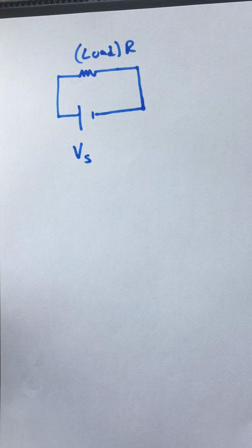Right? This is pretty standard at this point. I'm hoping we're seeing our way through it. Nature hates change, right? So any EMF induced in the coil is going to be such that it tries to counteract the change in flux. The upshot of that, mechanically, is that it controls the motion. It's a magnetic braking effect. It doesn't necessarily stop it, but it provides some sort of physical, mechanical resistance to the motion.